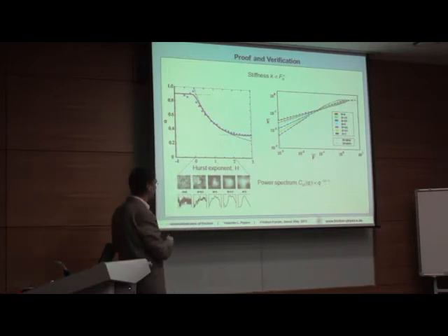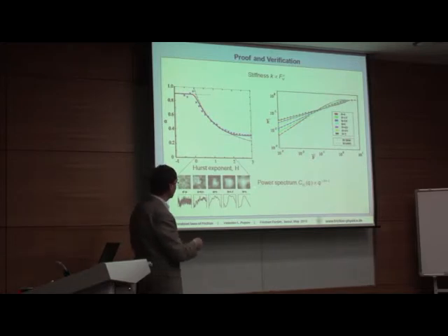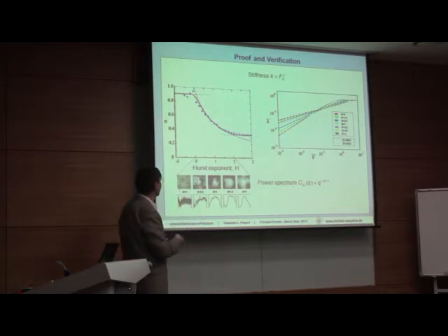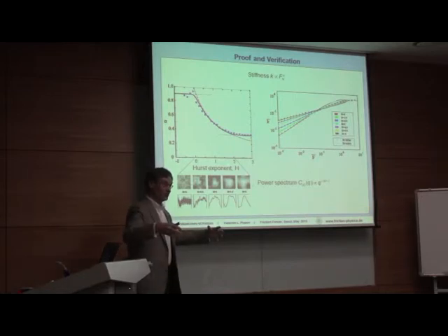Here are some kinds of self-affine surfaces with Hurst exponent 0 up to Hurst exponent 2. And this spectral density, one-dimensional, then has this form. It is a power function of the wave vector. We consider this sort of densities even in this region and in this region, even in a more white region. Completely, this is a complete white noise surface, so to say.